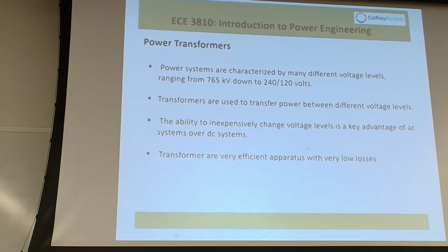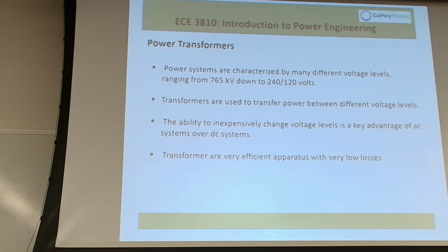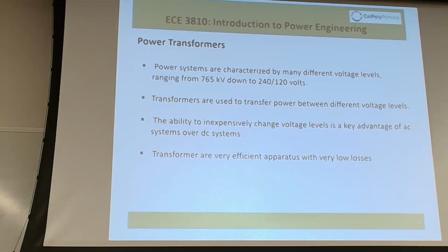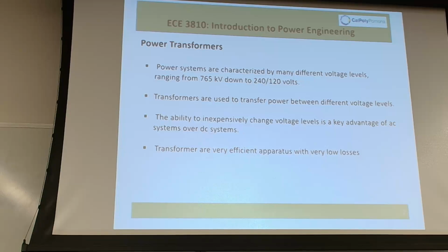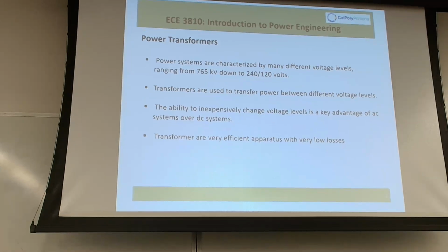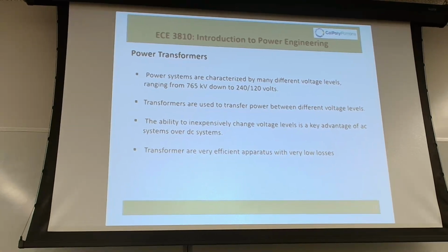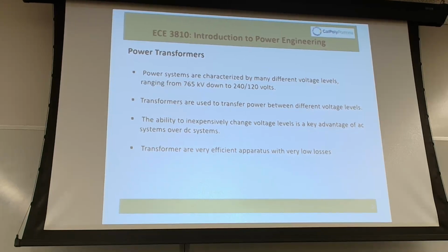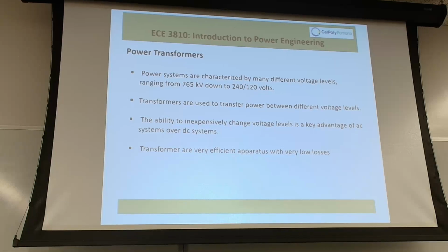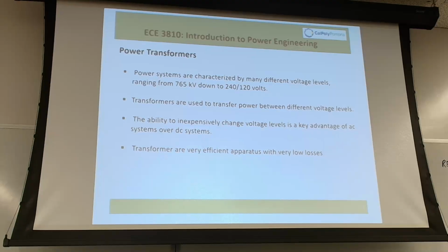Okay, so power transformers. There are all kinds of transformers, by the way. There are current transformers, potential transformers, power transformers, and other types that are used in the industry. Some of them are actually starting to merge now, and I'll mention them along the way. But really this class is focusing on power transformers, transformers designed to transfer energy from the primary to the secondary side. The main goal is to step up and step down voltages on a power system.